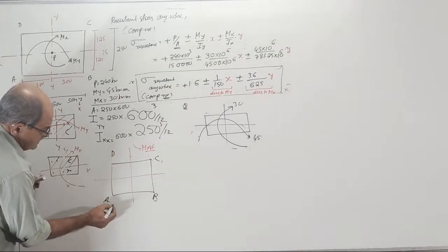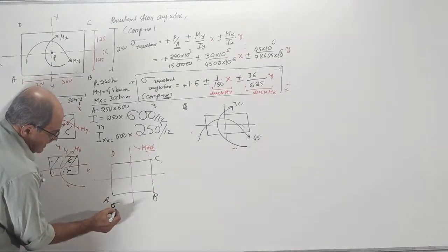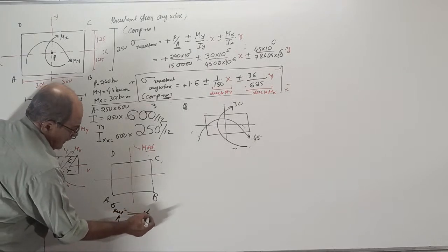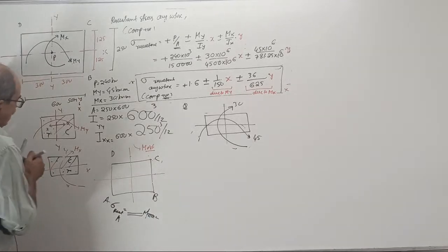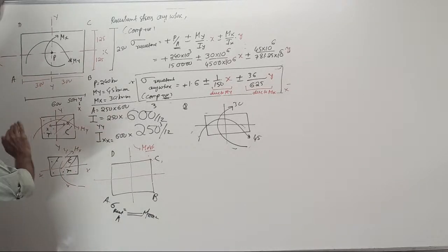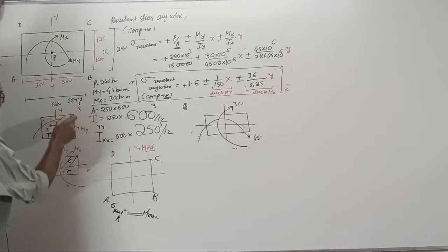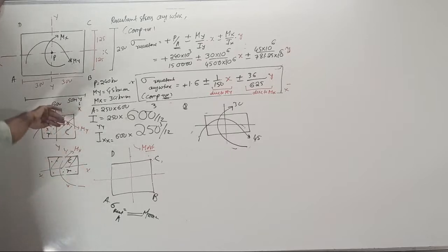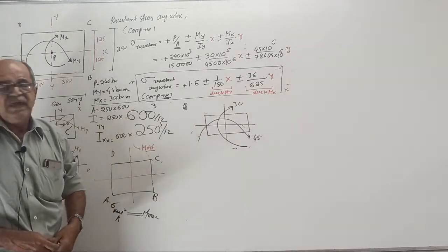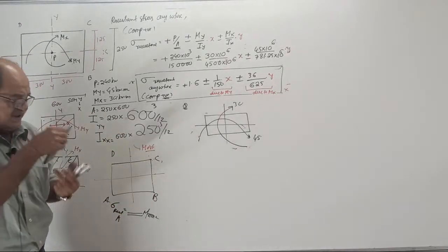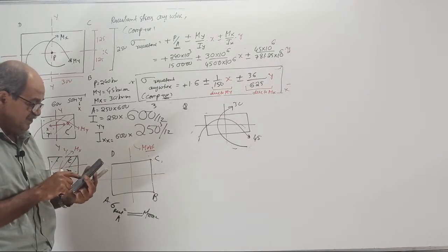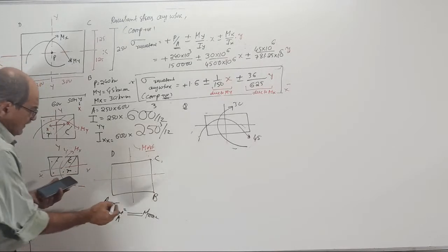Therefore, tell the answer. What is the resultant stress at A? Answer fast, in Newton per mm square. When you consider My, these 2 are compression, these 2 tension. When you consider Mx, this way, these 2 compression, these 2 tension, as told last time. Therefore the stresses we got yesterday are: at A, minus 7.6.